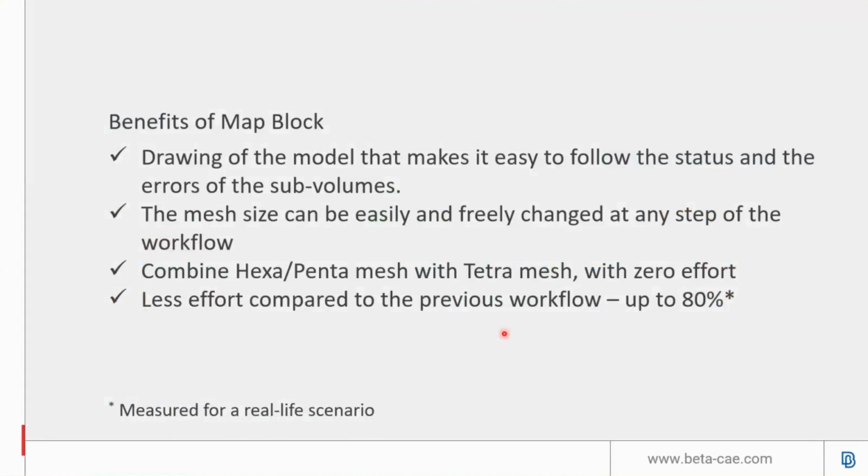The benefits of MapBlock: a drawing of the model that makes it easy to follow the status and the errors of the subvolumes. The mesh size can be easily and freely changed at any step of the workflow. Combination of hexa-penta mesh with tetra mesh with zero effort can be achieved. It takes less effort compared to the previous workflow, and 80% less time is needed.